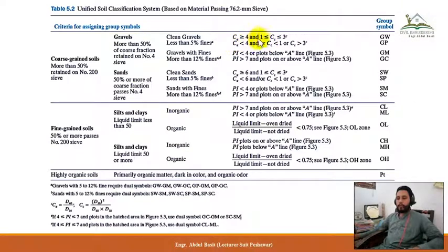This is the uniformity coefficient and this is the coefficient of gradation, Cc, and simply these can be calculated by Cu, which is d60 divided by d10, and Cc is d30 squared divided by d60 multiplied by d10. Okay, so this was discussed in chapter number 2, so you can go through those lectures to recall this idea of the coefficient of gradation and the uniformity coefficient.